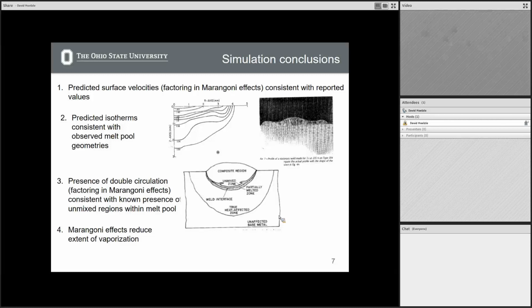So the point of the weld is to smoothly join two metals together to form an alloy, right? Perfectly joined alloy. But this always happens, where you get a region of unmixed materials in the middle of the weld. And they are saying this is due to the stagnation point in the weld pool convection. Because there's stagnation, there's no metal flow happening, and so the two adjoining pieces of material can't actually flow into each other and merge. Does that make sense?